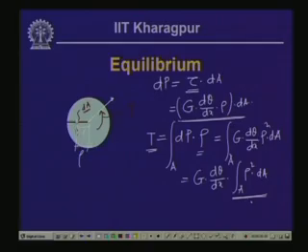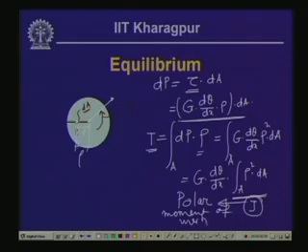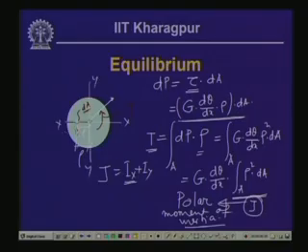So, this we generally designate as J, and J we call the polar moment of inertia, and as you know this is the sum of the moments of inertia about the x and y axes. So, J is nothing but equal to Ix plus Iy, where Ix is the moment of inertia of the section about the x axis, and Iy about the y axis, and in the perpendicular direction, which we call z, we add up the planar moments of inertia to get what we call J, the polar moment of inertia.